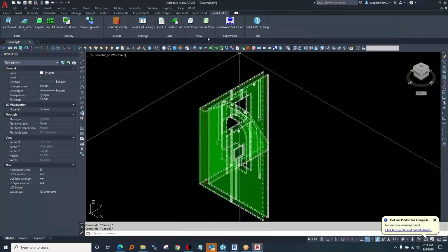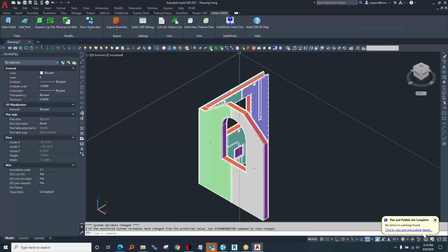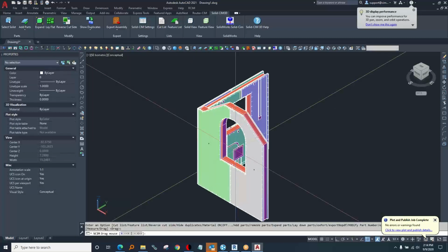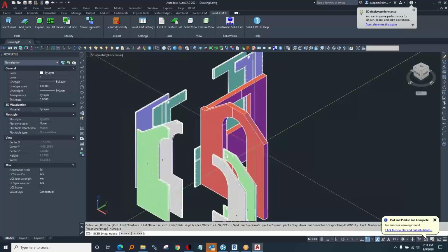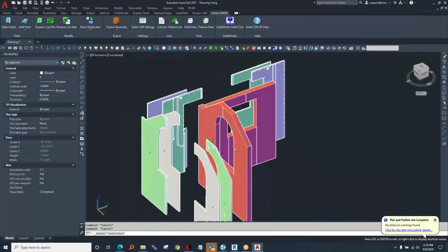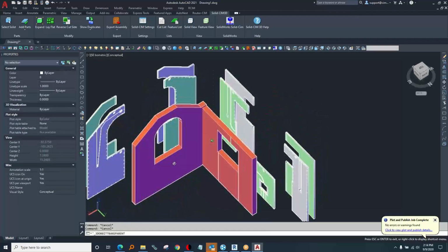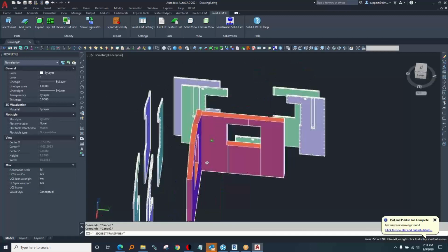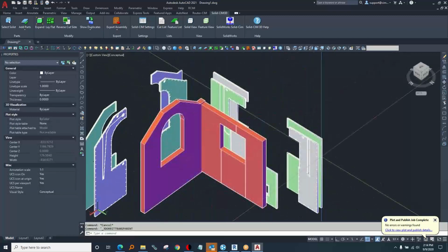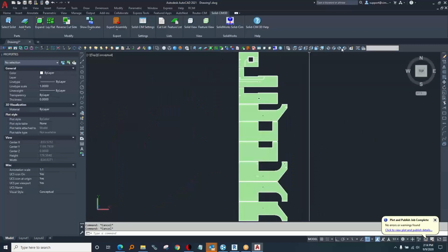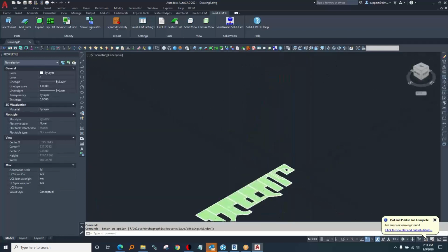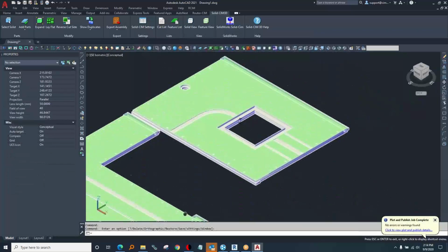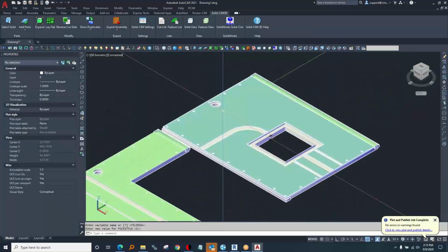Now it does leave you here in AutoCAD, so if you like, you can do an expanded view. Hold the mouse down and drag that out. You could see that we had a setting there that ignored the 5-inch thick material that's red, but everything else is found. And then here's the lay flat. Lays those parts out flat for you. And that's where we got the feature recognition and geometry on different layers.